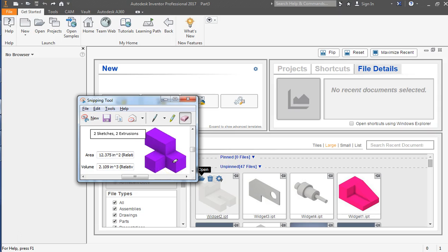When I model this, I can't make a shape where it's going to extrude maybe 1 block in one direction, but 2 blocks in another direction, all at the exact same time. So I will have to use 2 sketches and 2 extrusions. So my first sketch will try to capture as much as I can. It'll be these 2 and then the 2 underneath it that are kind of offset.